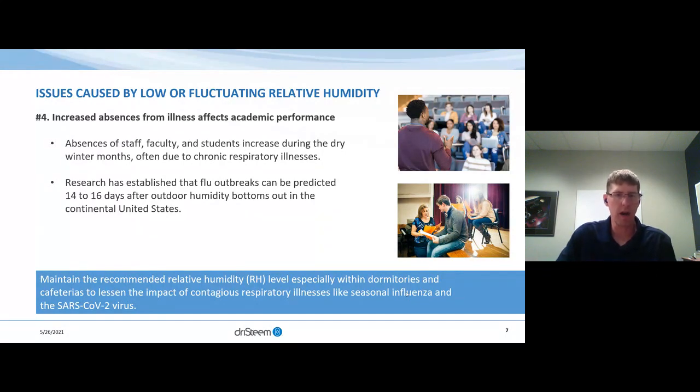And so those dry winter months, think of a cold climate. I'm in Minneapolis as an example. So it gets to be cold and dry. An ideal condition, if I take outdoor air that doesn't have a lot of moisture, I bring it into the space and warm it up, then my moisture content continues to drop. So my relative humidity within the space is lower. And that's partially why we're focused much more on this low humidity range, especially in colder climates and just in general, as we build them into spaces where it's warmer, that relative humidity will be lower.